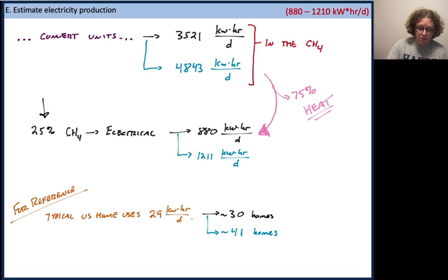All right, folks, so I hope that this helped you out. The goals for this exercise were to help you see the parallels between the aeration basin design and the sludge digester design, both microbially mediated processes where we've got to think about things like yields and saturation constants and growth and death rates, and secondly, to provide some context of just how much energy can be recovered from these systems by digesting the sludge that was a waste product from our treatment processes.